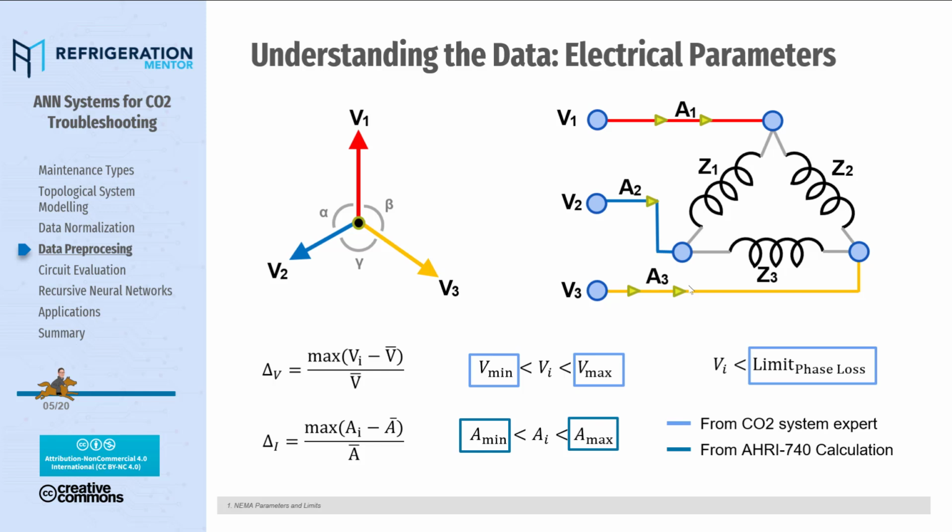From our point of view, the expert technician must adjust the limits of low and high voltage and some criteria, such as NEMA, which recommends a 10% factor of the nominal voltage for protection. A similar criterion can be used to determine the minimal voltage that our motor can manage, and mark this limit as the phase loss, even if we have an electrical protection. A new limit can be set in our pre-processing algorithm.